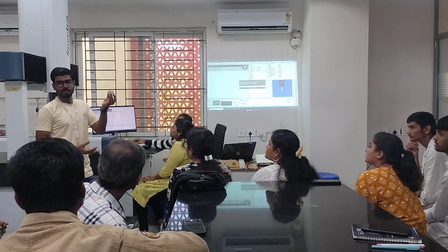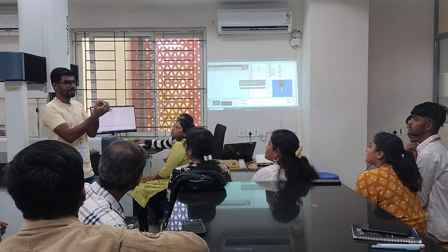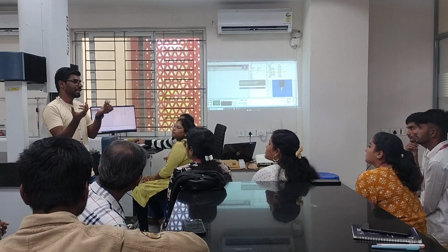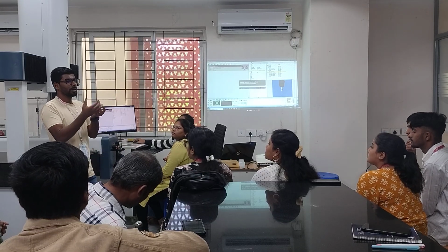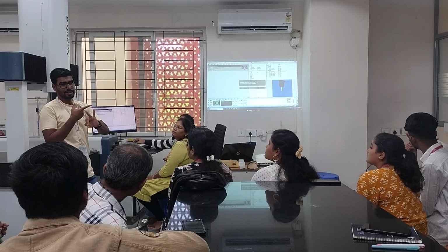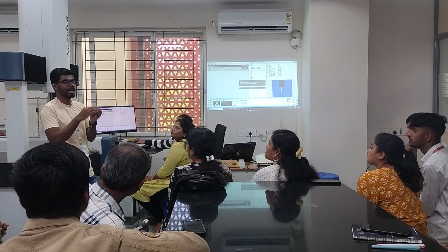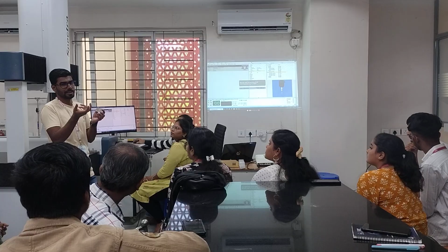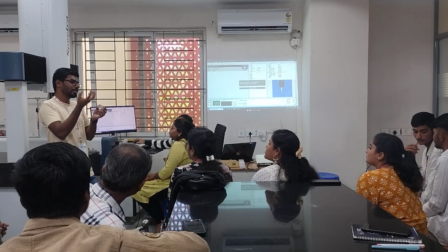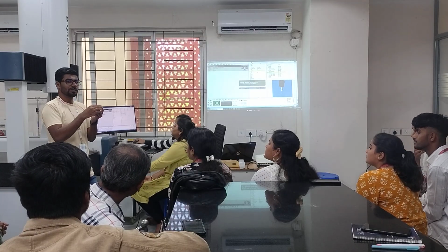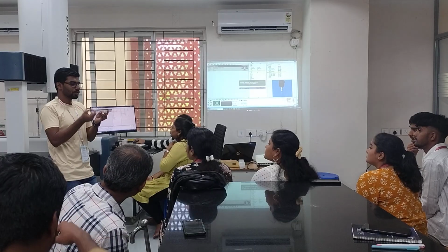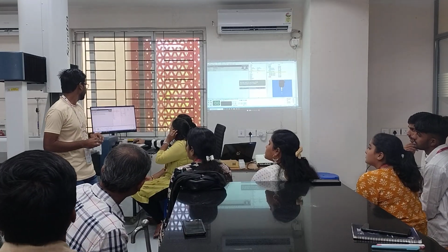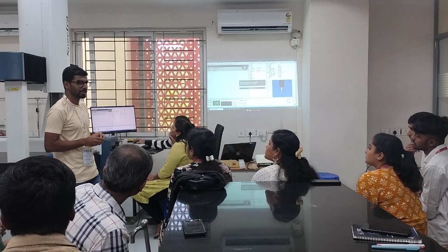Why is it so? It is less compared to the given design which I have made. Because whenever you are printing in DLP as well as SLA, there is some shrinkage happening. Printing is happening at some higher temperature. The resin is already heated. So when there is a cooling of temperature, it shrinks actually. So that shrinkage is visible here in the form of 39.39 something.